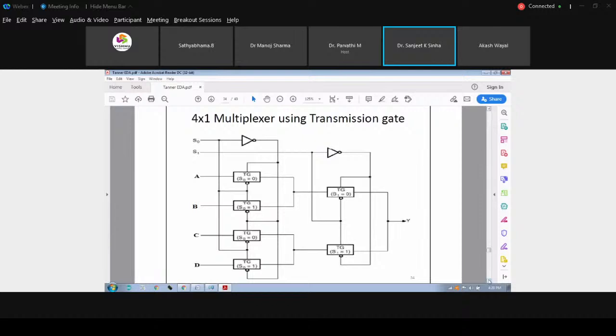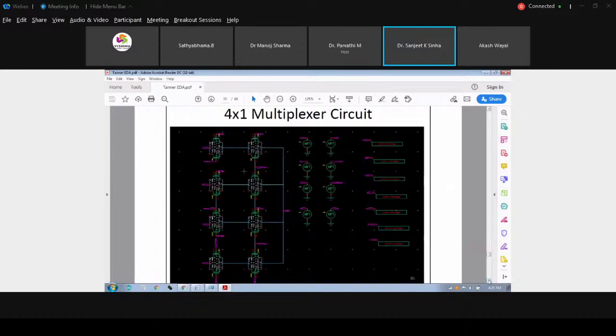So this is the typical implementation of this particular 4:1 multiplexer. So what will happen in a 4:1 multiplexer? We are having 4 inputs, we are having 2 select lines, and there are 4 options in these select lines: 0 0, 0 1, 1 0, 1 1. So we need 2 inverter kind of operation with those select lines. That's why in that design 2 NOT gates are there.